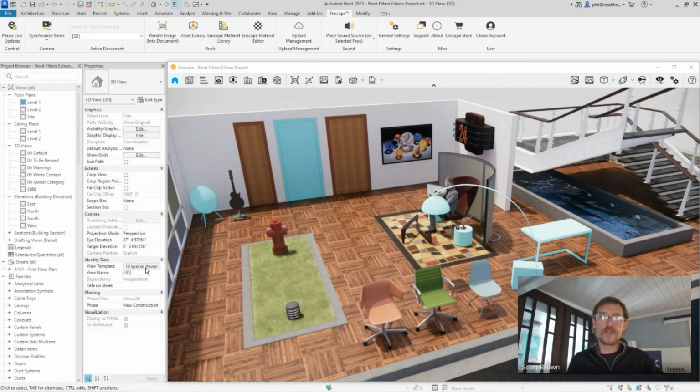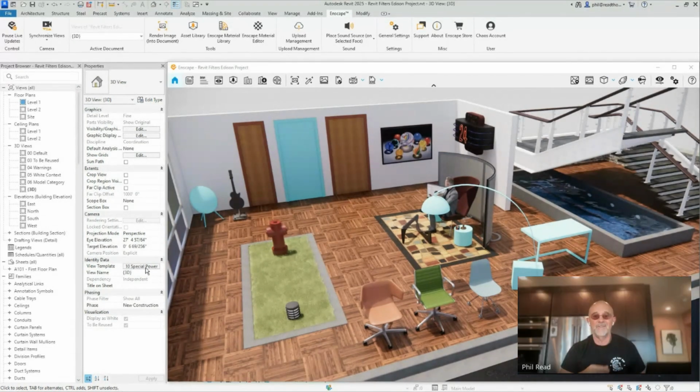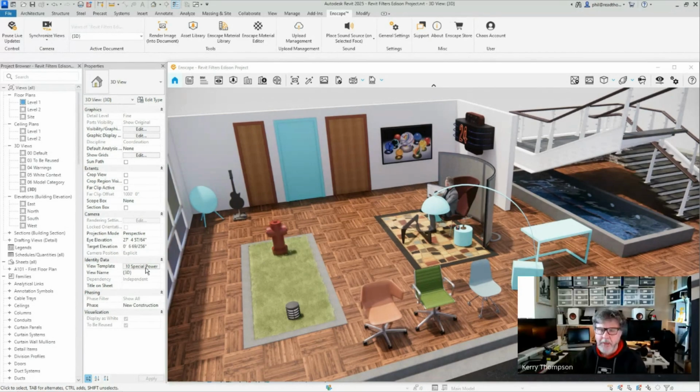So I love that you could isolate a specific scope and say, hey, let's have a meeting and talk about your scope. Here it is in this interesting format. Look, I love that section box tool. Pick something or pick two things corner to corner and just go section box. And the 3D view, if it's driving Enscape, by the time you flick over, it's already isolated that part of the model. But you could also stick that up on a website.